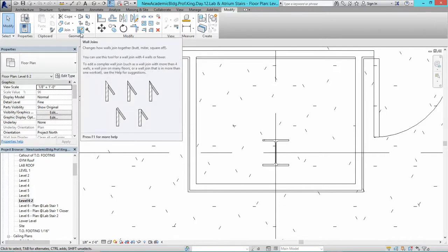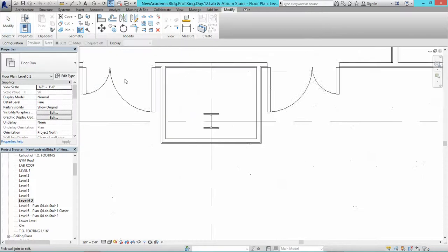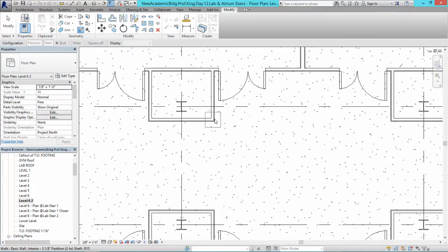So I'm just gonna talk about the wall joint tool in Revit. If you press that one and you zoom out, you see how it signals a little square in every joint part between walls, either corners or T shapes. So you first select the corner you want, and then here in this toolbar, it will give you different configurations.